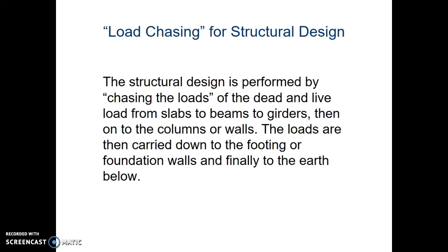And then load chasing for structural design. The structural design is performed by chasing the loads of the dead and live load from slabs to beams to girders, then on to the column or walls. The loads are then carried down to the footing or foundation walls and finally to the earth below.